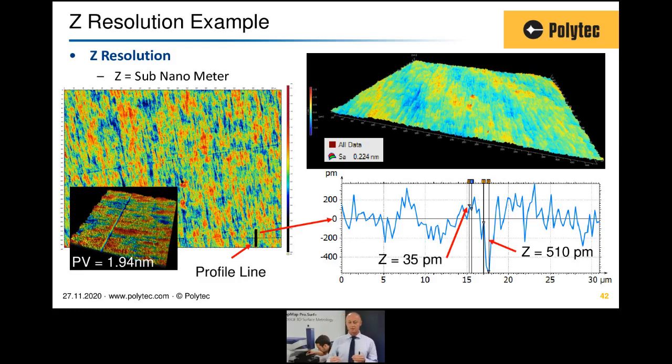At this quasi atomic level, we always ask, are we measuring a real function of a surface? With the human eye pattern recognition, if you measure, move 50 microns, measure again, and the patterns move, and then you remeasure the profile lines, if you get repeatability, then you can say, I am measuring a real function of a surface. So you can get a good indication of whether we're seeing a real representation of a surface. And that's exactly the exercise I went through on this particular surface.